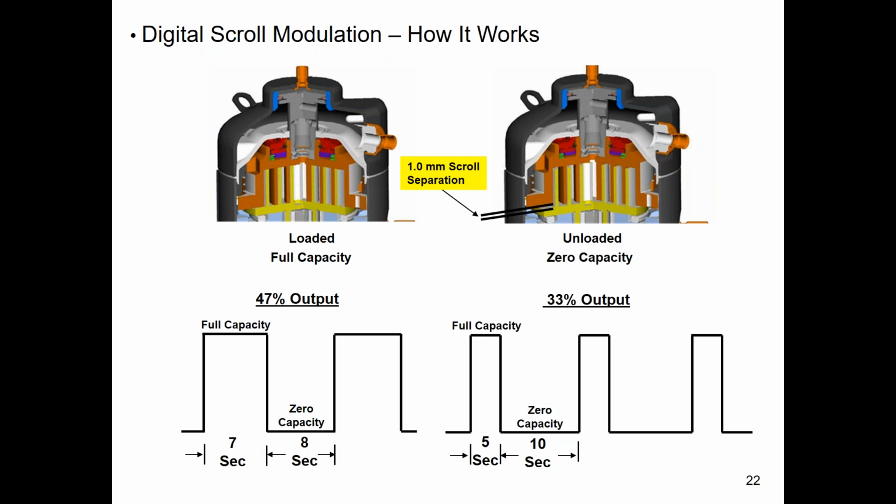Juma asks, how can you avoid vibration leaks, specifically in 25+25 TR tandem compressors? He's probably talking about the discharge T connection where they're headed together. I'm assuming that's what you're talking about. Usually if that's happening, there's another problem. We've got abnormal vibration coming off of one of the compressors or multiple compressors due to a slugging issue or what have you. So really need to address the source of the vibration, the compressor itself.